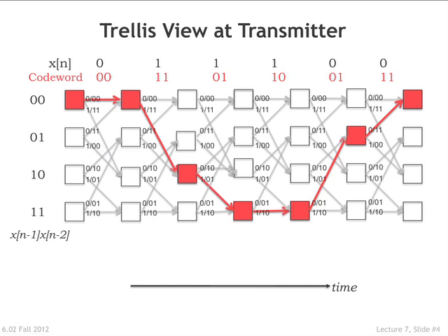So what we're saying is now, suppose you're starting off in the 0 0 state, and you get this sequence of message bits. So 0 1 1 1 is your message, and then you bring it back to the 0 state again by appending two zeros. What's the path that you traverse through the trellis? Well, you're starting off in the 0 0 state. Every time you have a 0 in the message, you take the upper branch. Whenever you have a 1, you take the lower branch of the two that are available to you. So you can see very quickly how to steer through this trellis for any particular message sequence.